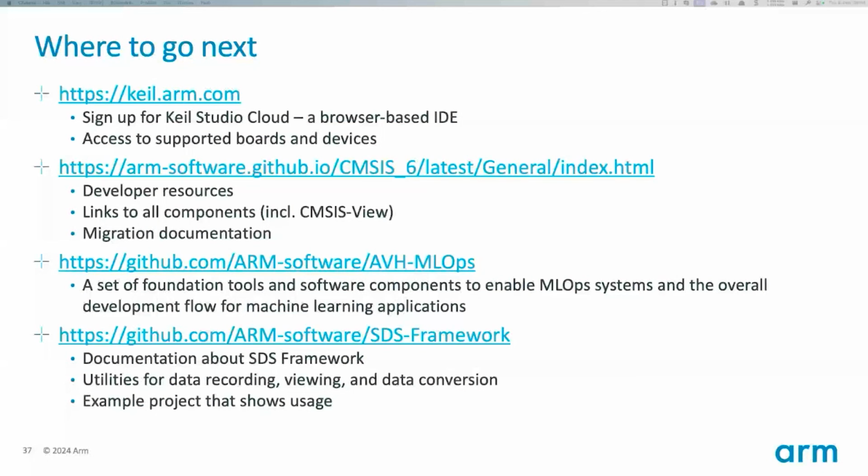So we have the first question. How does this virtual hardware layer work when you have custom chips that are ARM IP but not actual ARM chips? The ARM virtual hardware only simulates basically the core and its peripherals. So a Cortex-M33, an M7, and an M0 plus whatever. It does not really matter if it's not an ARM chip, as long as it's using one of the cores. You can do the simulation.